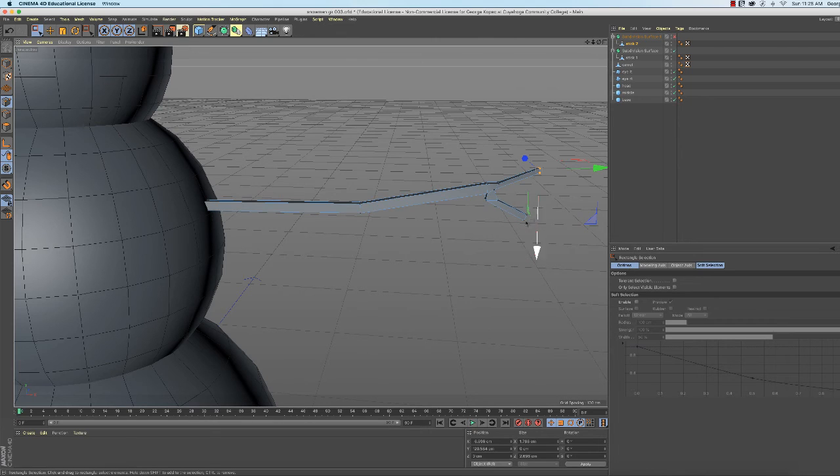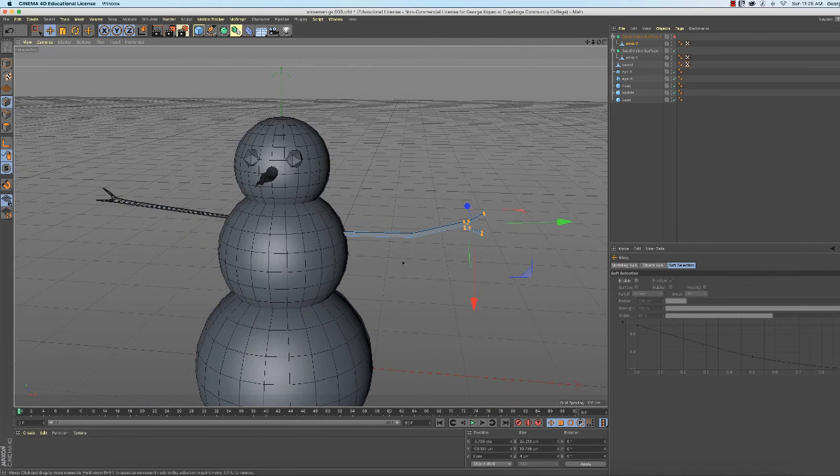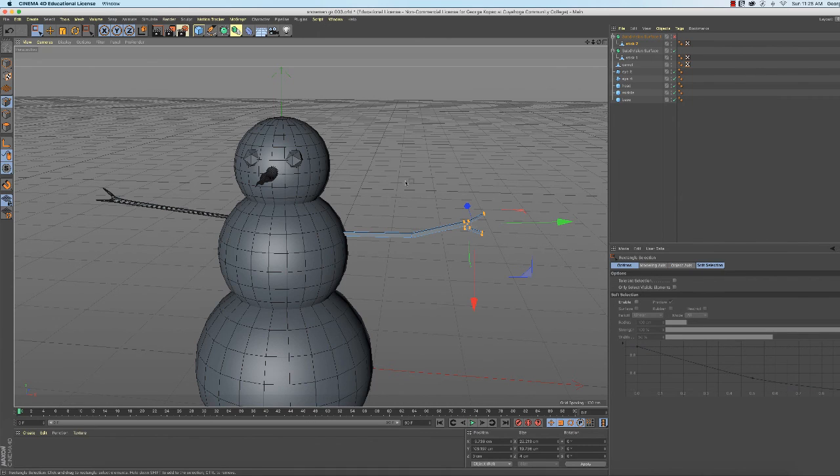As long as you have select only visible elements disabled, you can select the whole big chunk and move it up, or enable the rotate tool and make some changes. But don't make drastic changes, or else you'll destroy the geometry of it. You'll get some weird looking empty spaces and stuff. Okay, so that's cool. Alright, now let me hit spacebar to deselect. With the selection tool, I'll just select anywhere to deselect. In the object manager, I can deselect there.